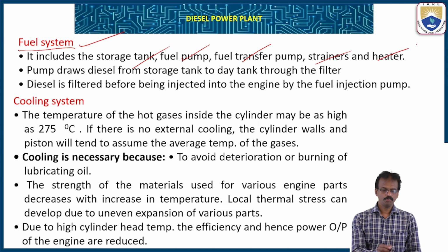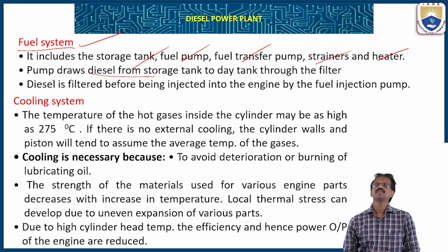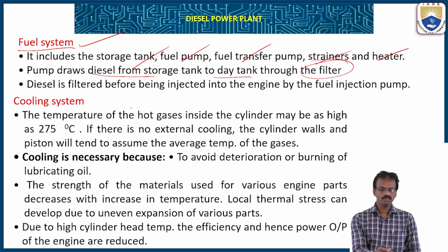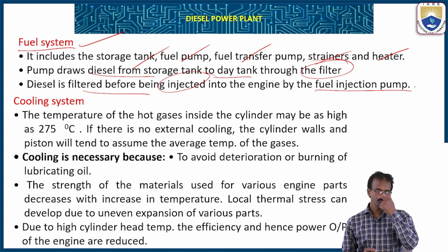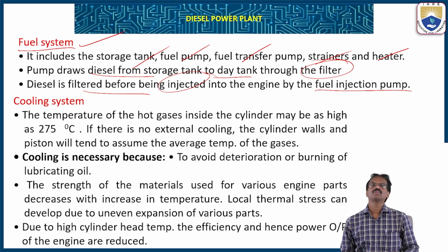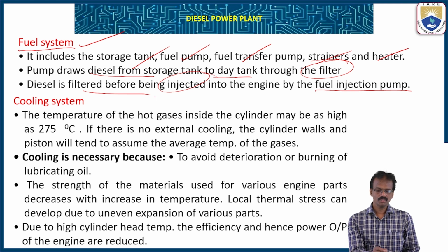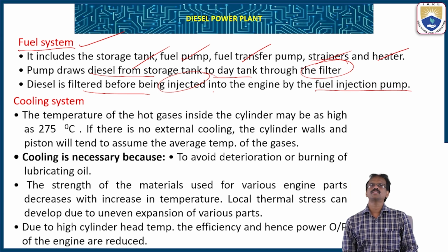Okay. So pump draws diesel from storage tank to day tank through the filter. Next, diesel is filtered before being injected into the engine by fuel injection pump. So this is the fuel supply. So this is very important. So after filtration, the fuel is injected into the engine.